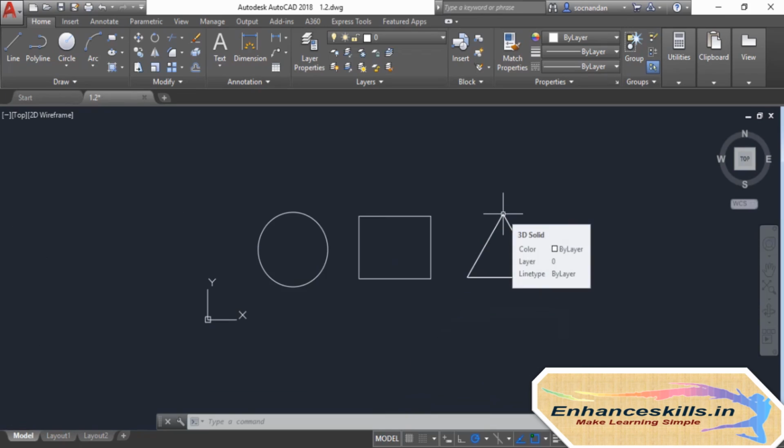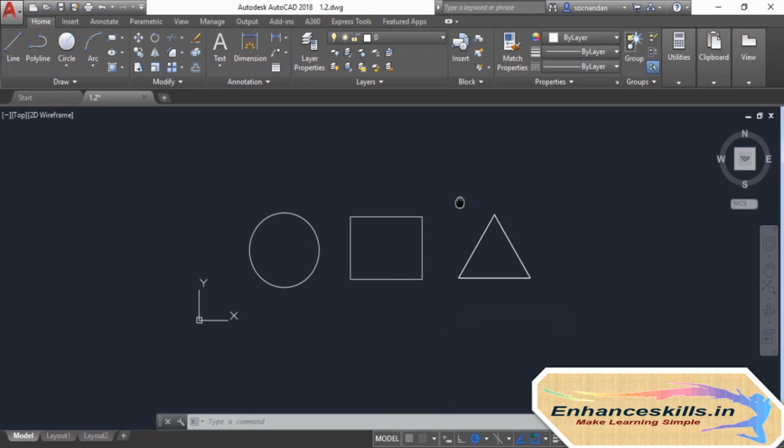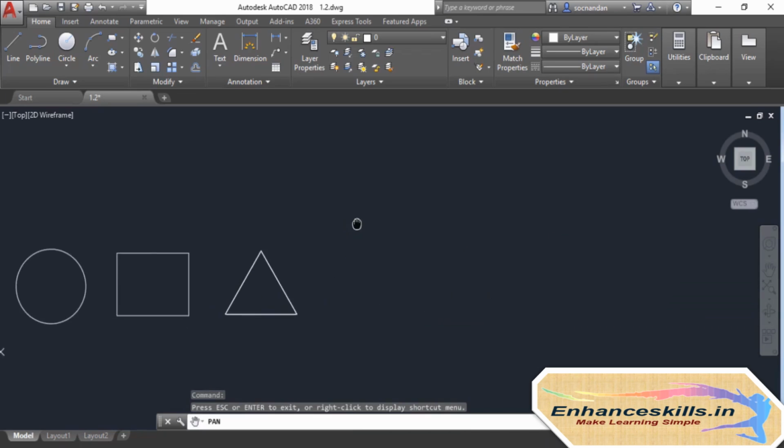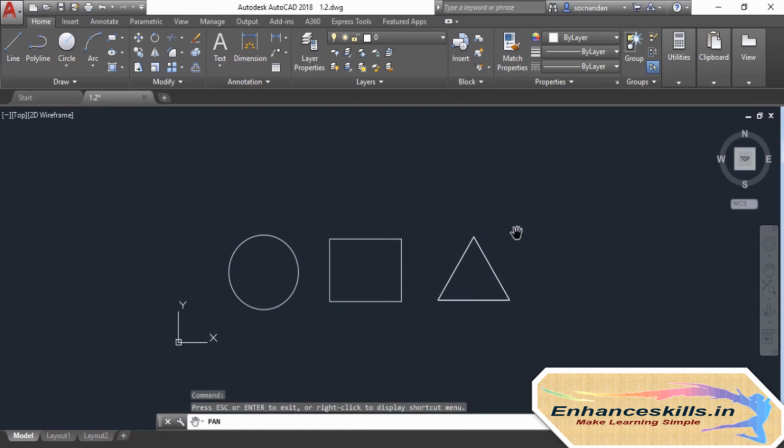In order to pan this drawing, or move it in the drawing area, simply press and hold the mouse wheel, and the cursor will change into this hand, and now you can move it in the drawing area like this. You can also access these navigation tools directly from the navigation bar. Here we have this Pan tool. Simply select it, and now you'll be able to pan the drawing.